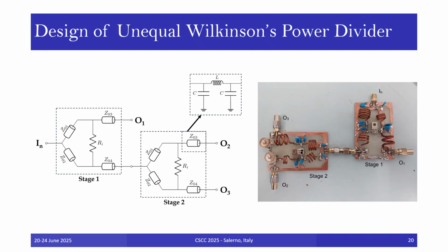Although N-way power splitters have been proposed in the literature, in this work, an alternative 1 kilowatt modular two-stage power splitter is proposed. The proposed solution facilitates the optimization and testing of the lumped component implementation by independently designing the component values of each stage and limiting as much as possible their associated parasitic components. While SMA connectors were used for prototyping purposes, these were eventually changed to N-type connectors in the final version.